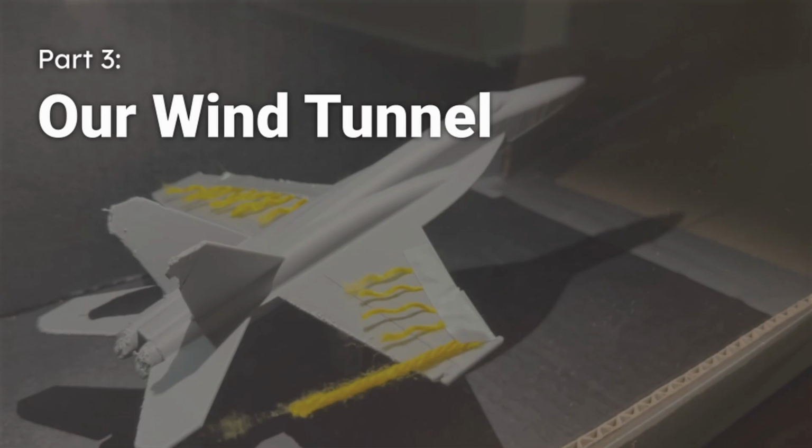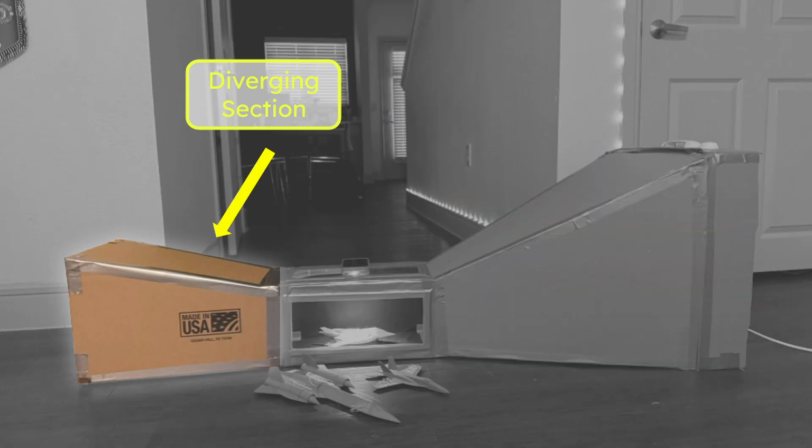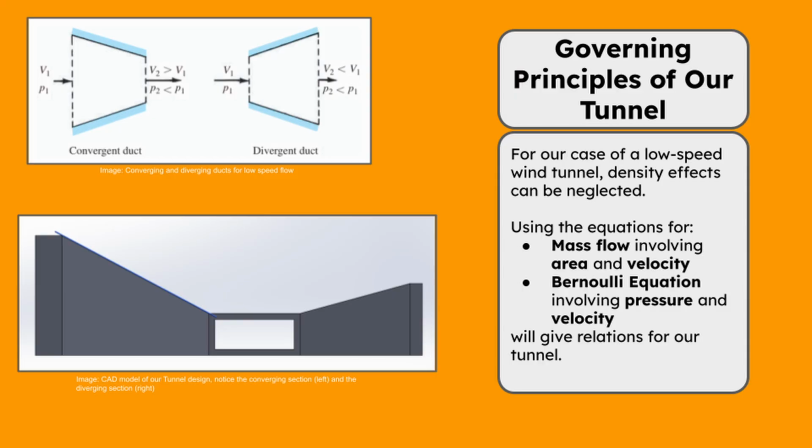To demonstrate our findings with real-world models, we constructed a scale open-section wind tunnel model out of common, everyday materials. The model features a fan, converging section, test section, and diverging section. The geometry of a wind tunnel is the key factor that makes it effective at producing high-speed airflow. The converging section changes the velocity of the air from low speed to high speed by changing the area of the throat. This process is reflected by the conservation of mass flow.